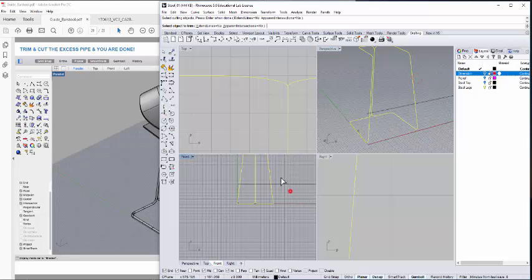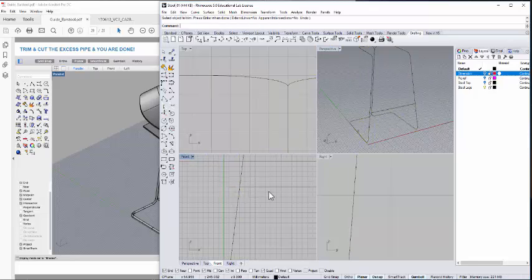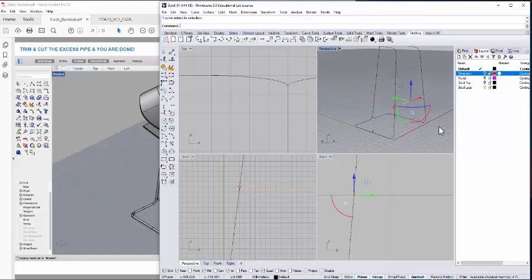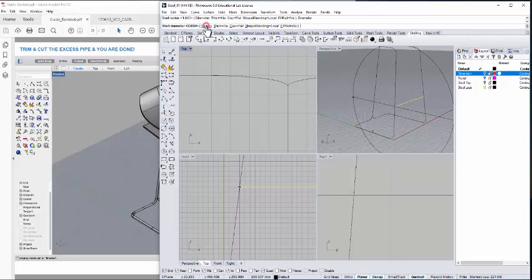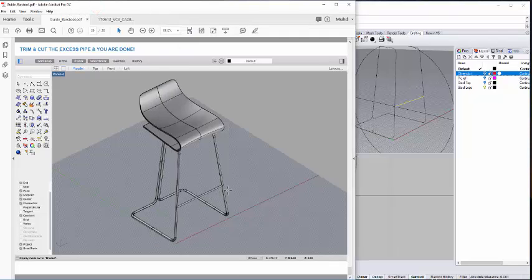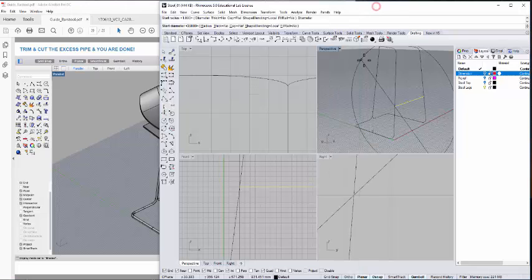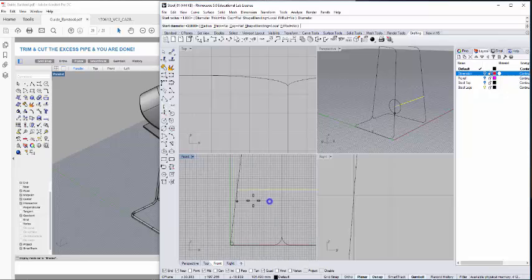Trim again. Okay, so now it's possible. Why? It wasn't snapped just now. Here what we can do is type pipe. Just now was 15. So what we can do is a quick diameter on maybe the legs, instead of 15. Because if you have 15 and 15, it won't touch the edge here. So for this portion here, maybe we reduce to 10. The center, enter.